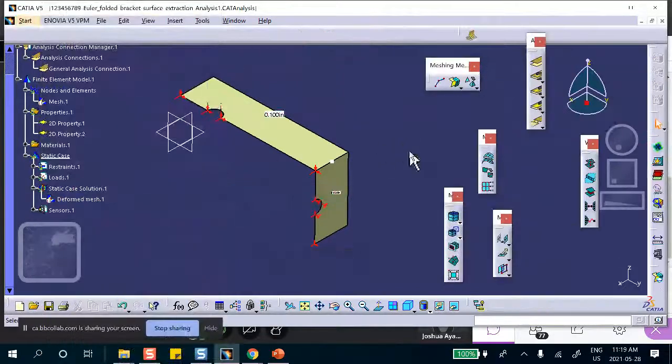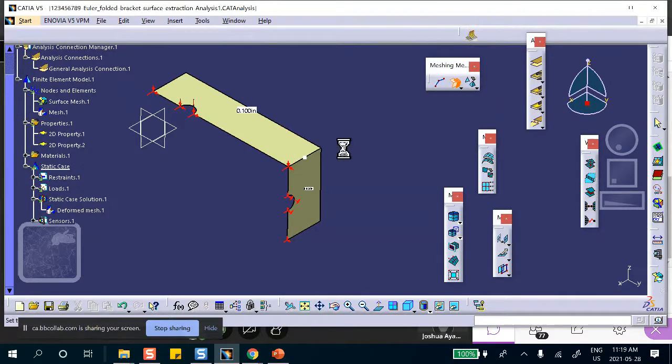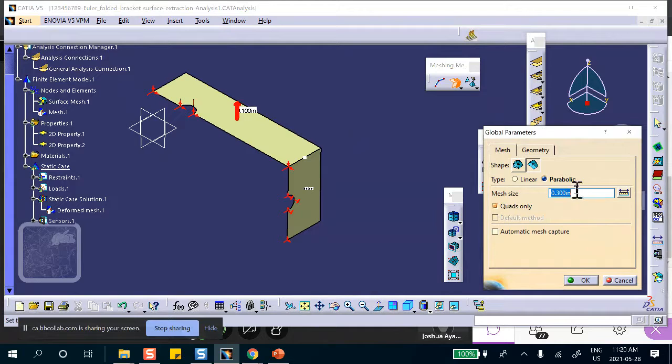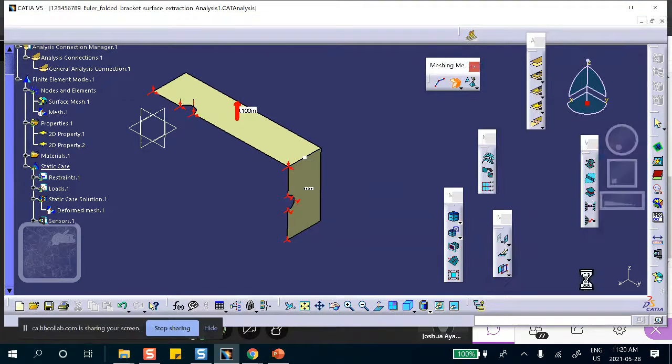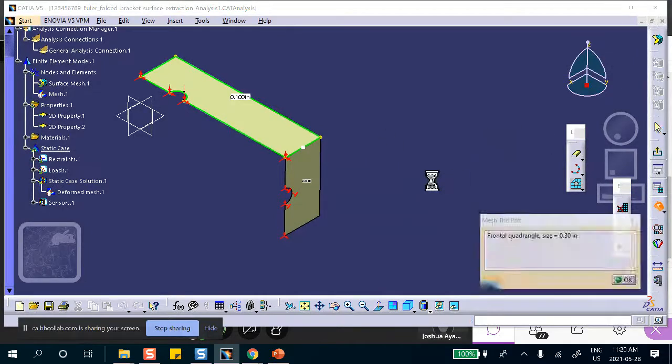Advanced meshing tools. And there's something called surface mesher right there. Incidentally, let me show you. Cancel that. Notice that you know this. This is the one that we have been using for the last 2 days. This is surface mesher. I clicked on it and I select that. And let me make this thing, I'll keep it as 0.3, no problem. Okay. All right. And mesh it.